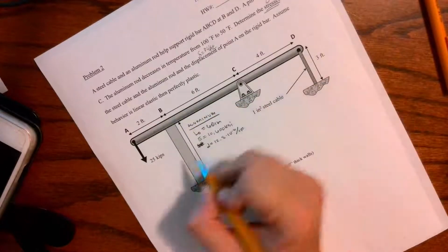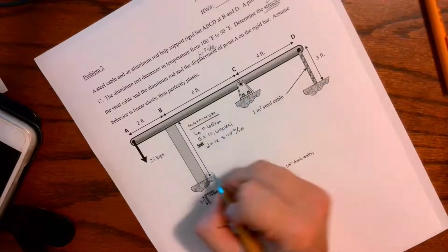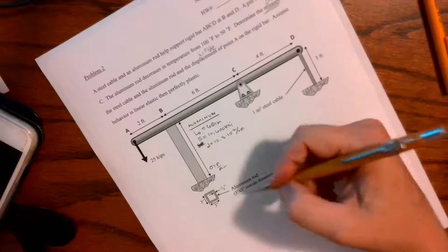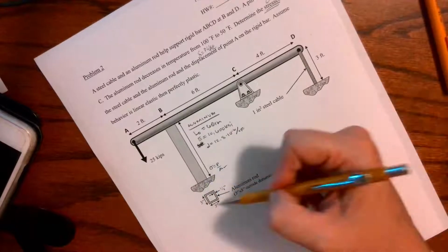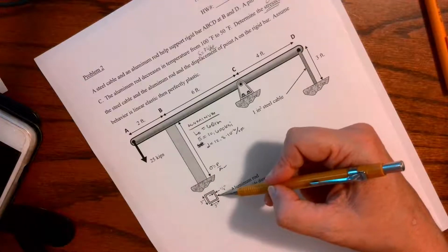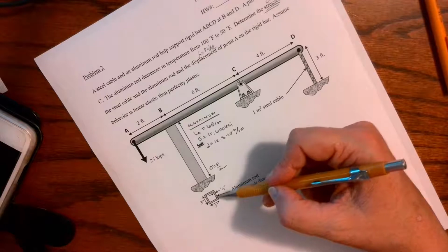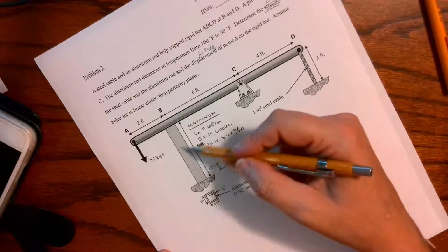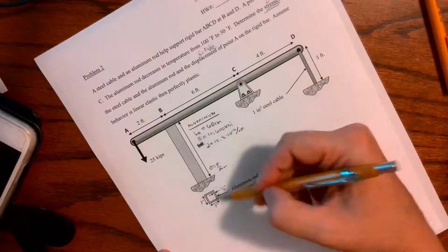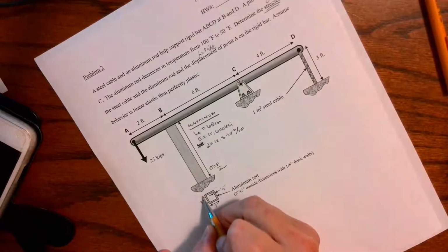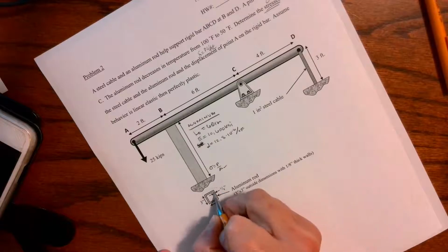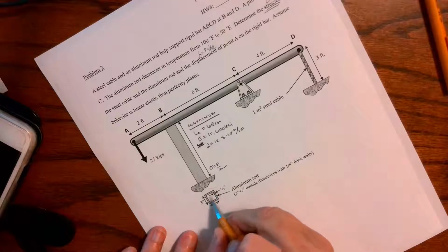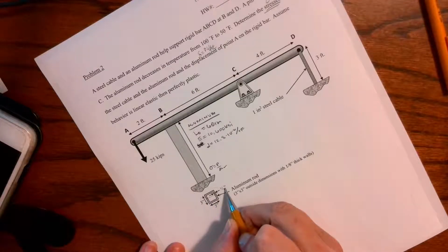So we need to find stress. If I need to find that stress equals P over A, I need to find the area. Okay, this looks a lot like the problem I just worked with torsion, where we did a thin-walled problem in torsion. This is not in torsion, this is in compression. All I need is the cross-sectional area. So if the outside dimensions are 3 inches and I have a thickness of 1/8 of an inch on each side, then my total thickness when I look across the 3 inches is 1/4 inch.